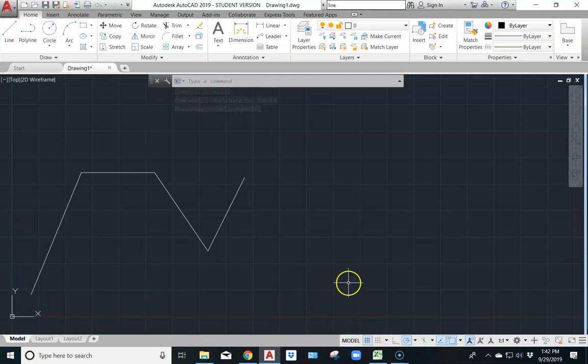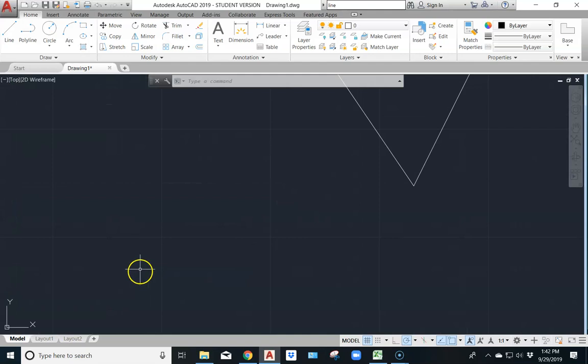We then have the grid in the background here, and you can turn that off or turn it on. If it's highlighted blue, it's on. If it's just white, it's off. And that grid can be used to snap to if you turn on the snap mode. And so you can set that grid to be a specific distance between each block on it, and then use that as something to help you with measurements if you want to. If I snap that mode on or off, then you'll see that when I go into the line command, it's now kind of giving me a little jog to those corner points for each of the blocks in order to make it easier for me to use those.